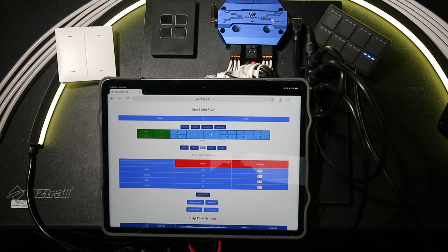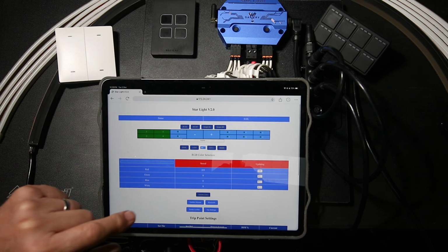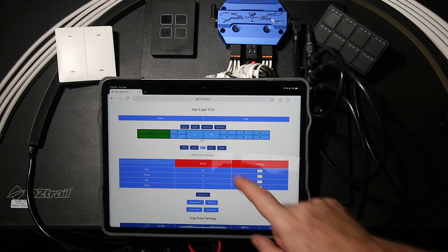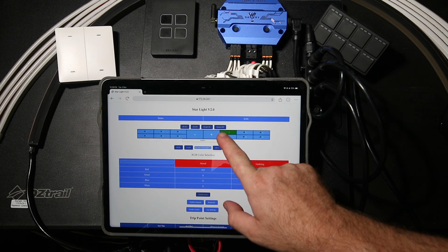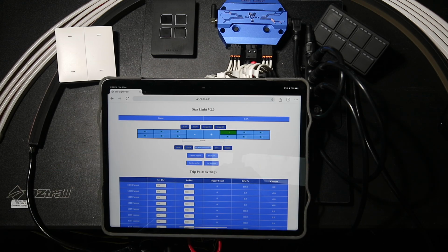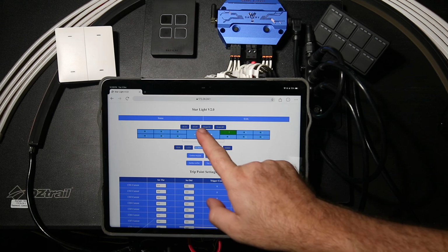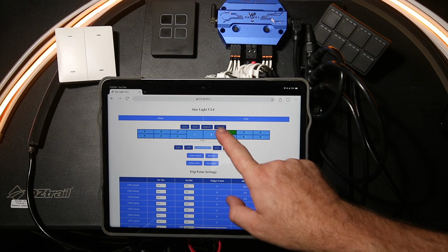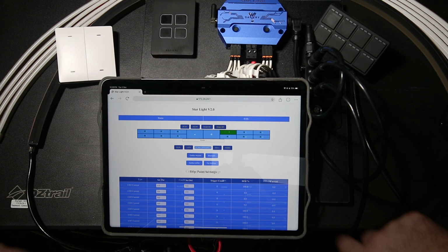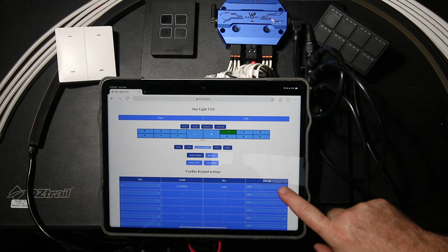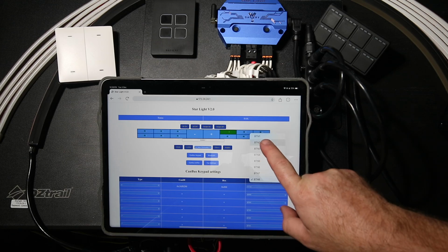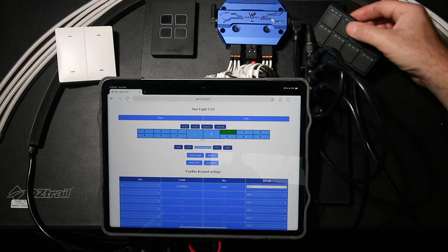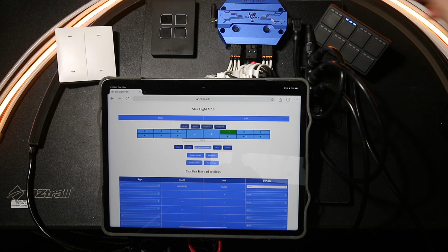We'll now go to just a single channel, and so to do a single channel, let's pick channel 7 there. We just select that channel. You can see single channel mode there, and having selected the single channel, we can turn it on and off. So there it is, on now, off. And if we turn it on, we can assign another button to it, button 2. And so when button 2 is pressed on that now, then channel 7 is turned on.